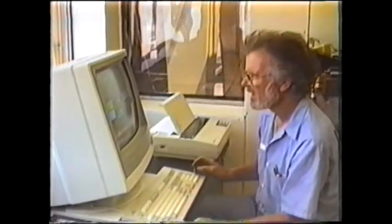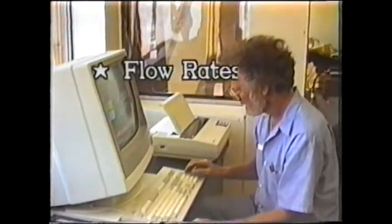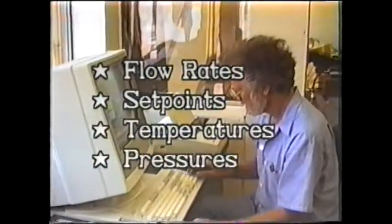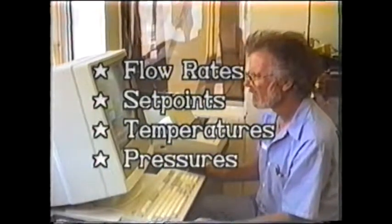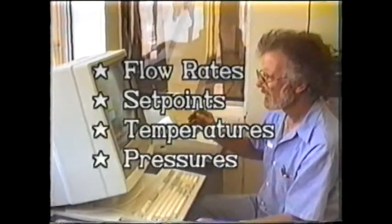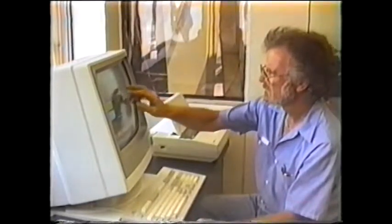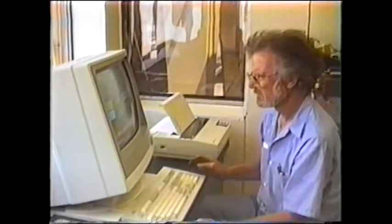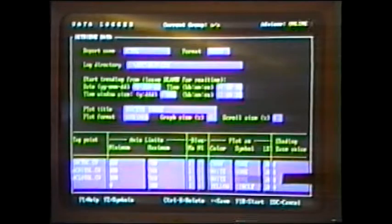Also recorded on the hard drive is every process variable. This means flow rates of all materials, set points, temperatures, and various pressures. This data can be recalled using the data logger feature, which is a historical data retrieval system. Through data logger, the operator can look back in time and find out the performance of any of these plant variables. The amount of history available is limited only by the available disk space. It is possible to store up to a year's worth of information.